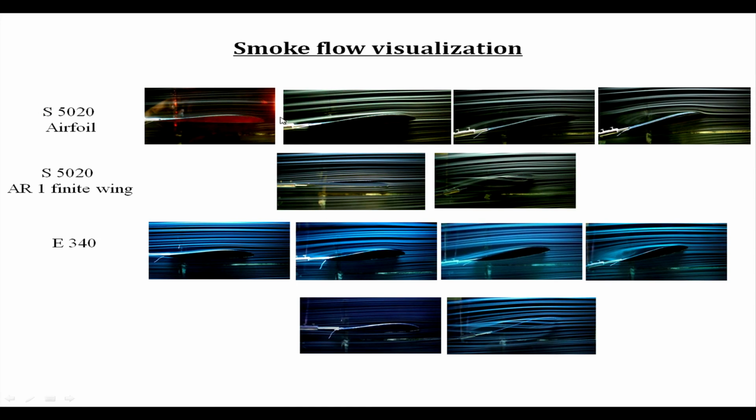So, we tried to do some smoke flows, and on the airfoil sections you can see some slight separation setting in here. The bubbles, you do not see them very clearly. I guess I should have given you a bigger picture. In one of the cases we could get the bubble more prominently, but here the separation seems to increase as the angle of attack increases almost monotonously.